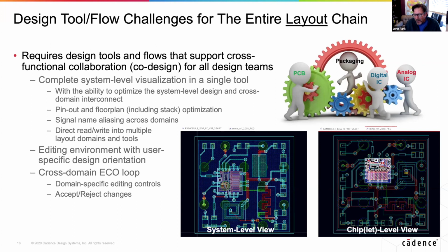And then the picture on the right shows you the chiplet designer's perspective, which is different. The packaging isn't maybe as important to them, the chip is. So you'll see, this is the same exact design. The design tools need to say, okay, I'm looking at the chip now. So now I'm looking from top metal layer down. It's not flipped. You don't design a chip, you don't place and route a chip as it's being flip chipped. The flipping happens in the packaging stage. So you see everything from the top metal layer down.